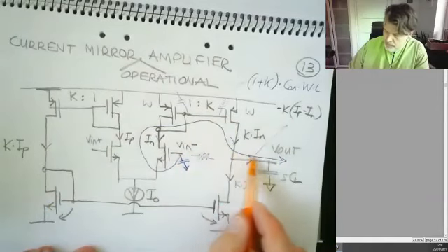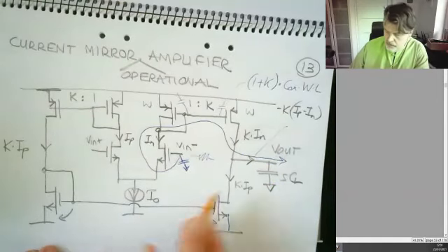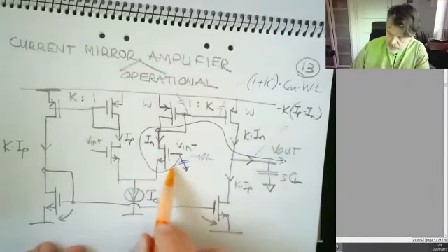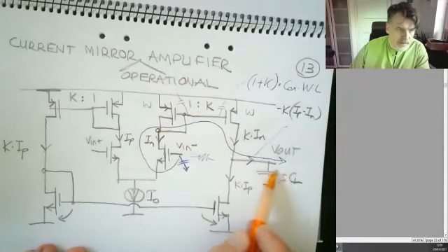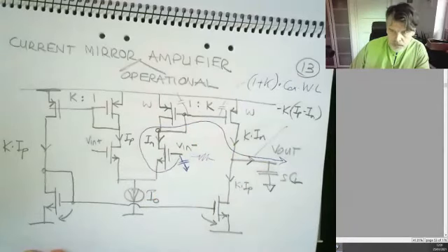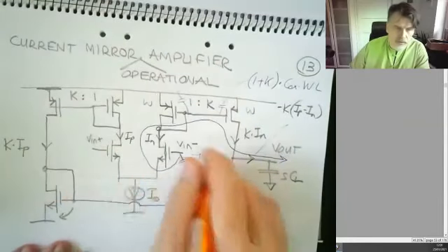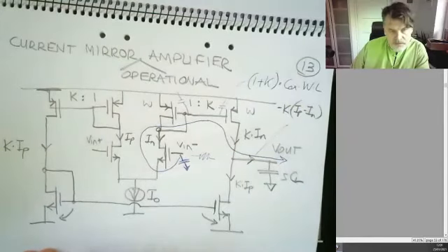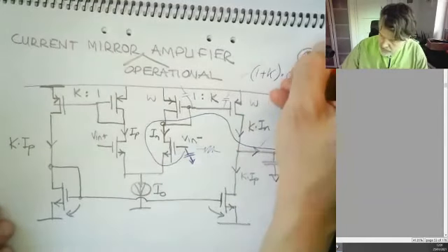And then you continue. Okay, you go to the output, then you have your final capacitor, which will give you a pole also. So in this particular case, if we have a good voltage source at the input, we can ignore that one. We bump into one pole here, and then we bump into one pole at the output also. So it's a good way to take any circuitry and just go through the signal path from input to output and identify whatever you might bump into. All right.